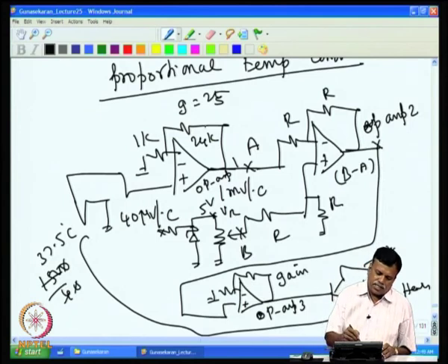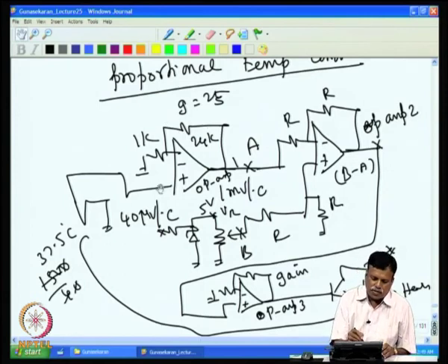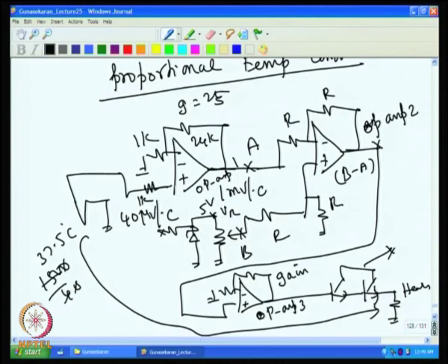Similarly, these resistors we have used are 24K and 1K, and if I use very high resistance, then I have to consider bias current error also. Of course, it is better to add here one resistance, roughly 1K, so that most of the bias current flowing here is equal to here and gets compensated. The parallel combination of these two should be used, and keep this RF and R1 at a lower value, so that even the offset voltage drift is lower.